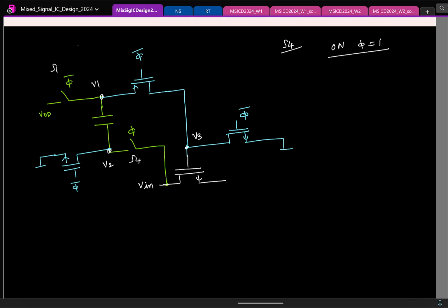There is not a lot of deep thought put to that, but sometimes simple thoughts work. But again, the control signal is a thing, because to turn it on, if we just give VDD, my source voltage will be at Vin. This will not be enough. So my gate voltage should actually go to VDD plus Vin, right?